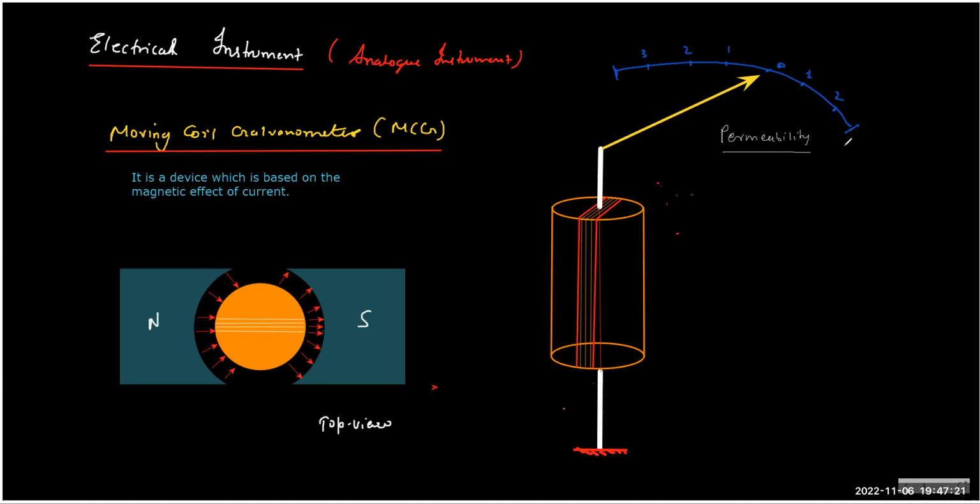What you see is this calibrated scale on which this pointer moves because of the twist of the loop. As the loop turns, the cylinder will turn, so there is a twist in the spindle, and the twisted spindle will let you see the turning of the needle.